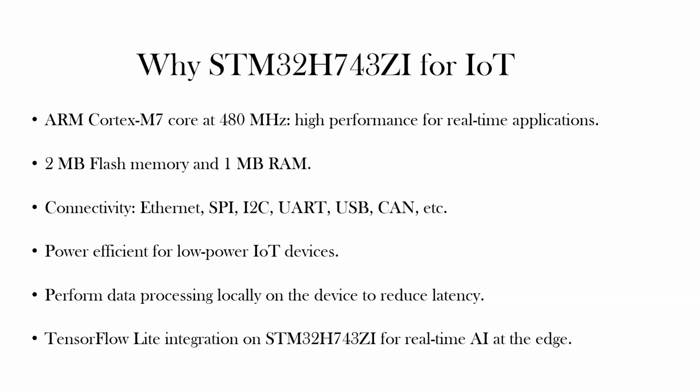applications. If I compare a microcontroller with a microprocessor, definitely a microcontroller is much more efficient than a microprocessor because it has all inbuilt peripherals. It's working on a complete flat memory model, unlike a microprocessor, which has a memory management unit, which creates latencies. On top of that, most microprocessors have some sort of OS, which again creates software latencies. When coming to the microcontroller, it works on a flat memory model, no memory management unit. It's all flat memory model.